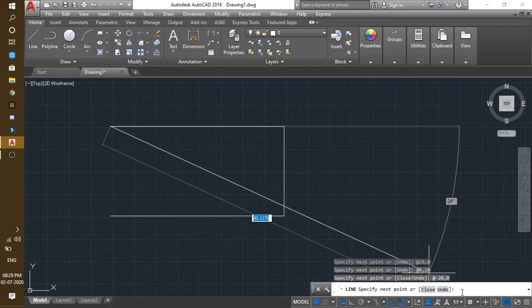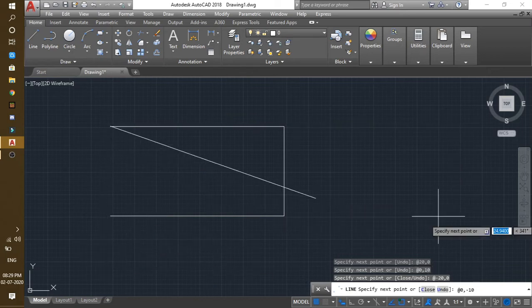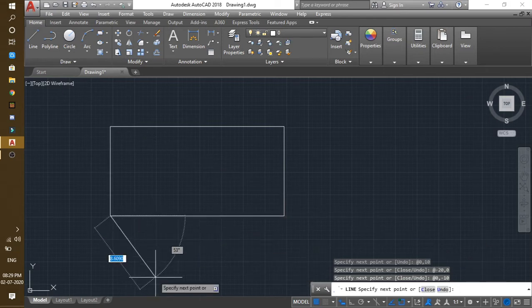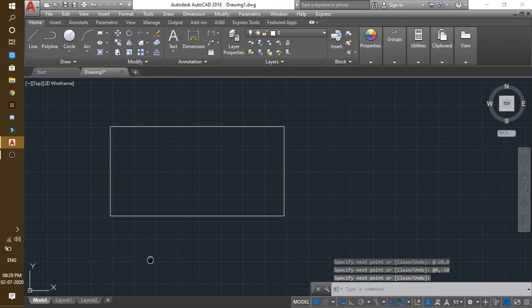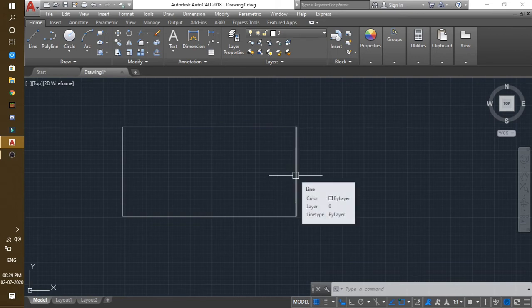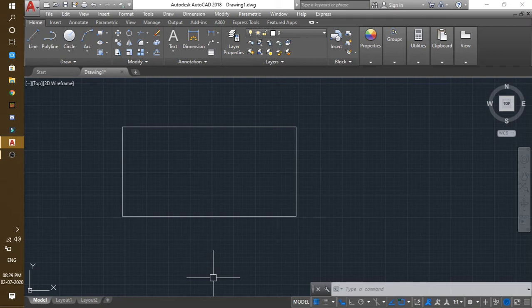Now at last press add. Now your x coordinate is 0. Press 0. Now comma, we will have to put minus 10 here. Why? Because again it is in the opposite direction. Just put these coordinates and press enter, and press enter again and your rectangle will be formed. This is a rectangle with length 20 units and width 10 units. It might feel complicated, but believe me, after you keep using AutoCAD for a while, everything just feels very natural and you will get used to it.